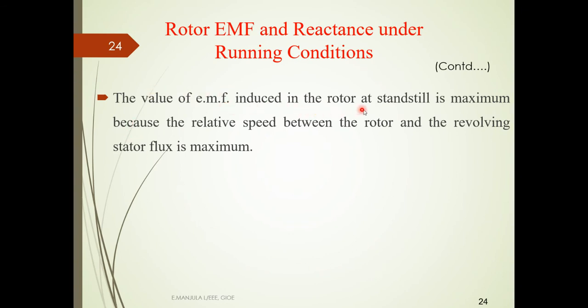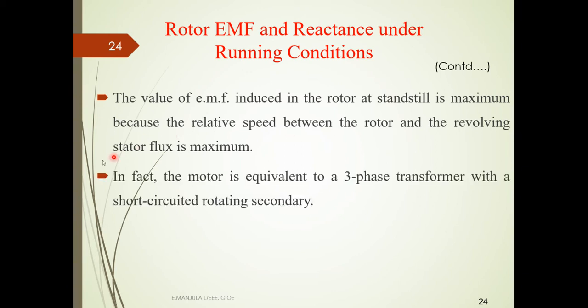The value of the EMF induced in the rotor at standstill is maximum. That is, the generated EMF in the rotor at standstill is maximum because the relative speed between the rotor and the rotating flux of the stator is maximum. In fact, the rotor is equivalent to the three-phase transformer with the short-circuited rotating secondary. So this induction motor resembles a three-phase transformer where the secondary winding is short-circuited.